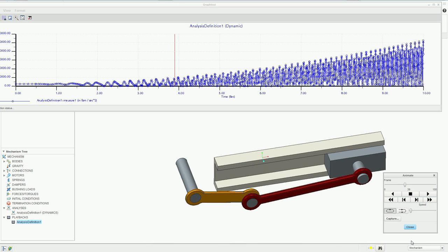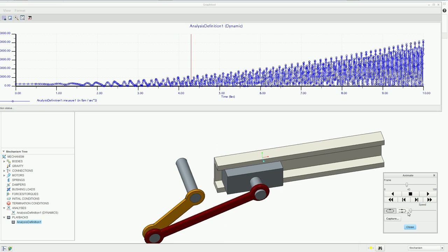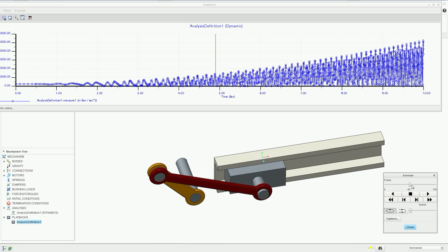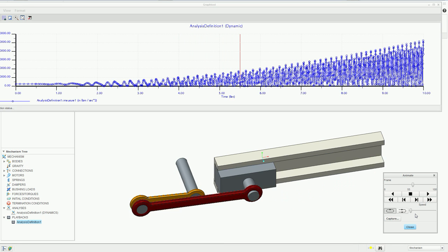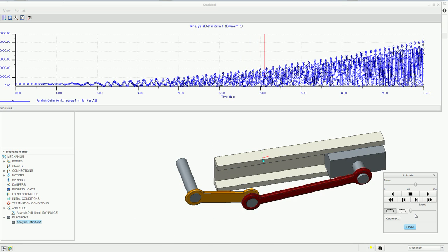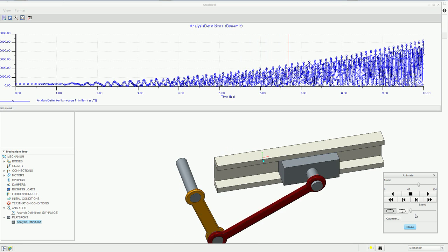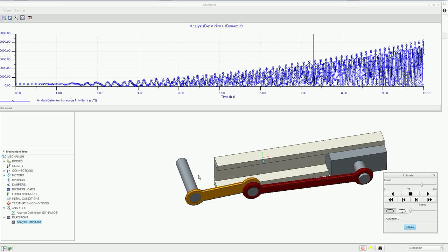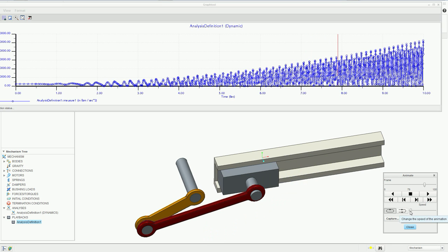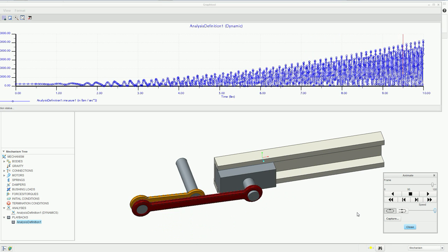Alright, so here's another point I can already make. Since we changed the frame rate to 10, you can see how it's jumping to the positions, and it's not as high quality as we would like it to be, is it? That's the reason why you would increase the frame count to increase the accuracy of the result. This is very choppy and it doesn't look as smooth.